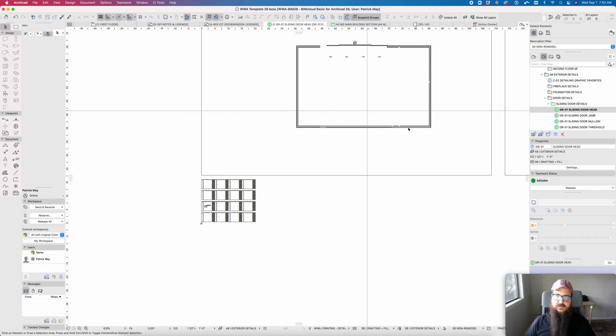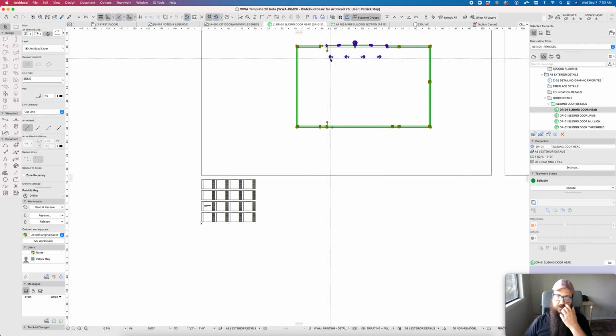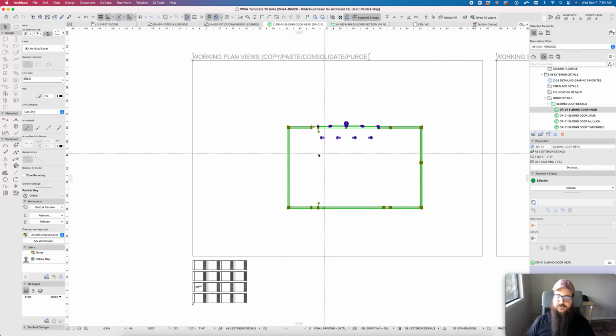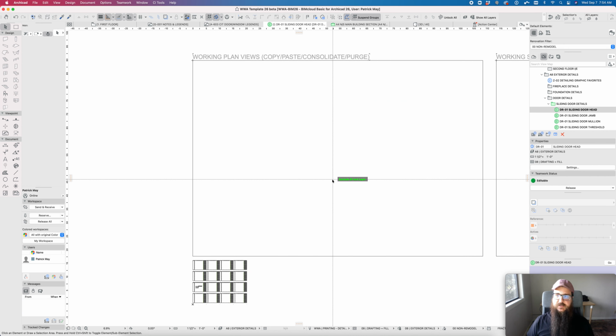One word of warning is that having huge model areas like this, copied and pasted and just kind of hanging out off to the side, can really create a lot of clutter. 2D content bogs down ArchiCAD, really almost worse than model elements and polygons. So if I just look at the fills here, in this really simple floor plan area, I've got 99 fills, 125 lines. These numbers easily get into the hundreds of thousands, and that much content in a single viewpoint, especially 2D content, we've seen files just really bog down and come to a screeching halt. So it's a really good idea to just delete that stuff when you're done.